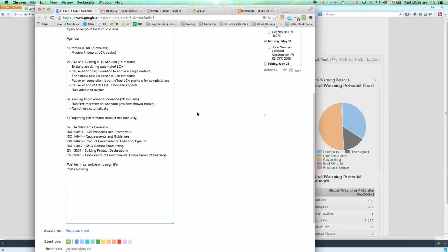You said you've been trained in NatHERS as well. Is that right? Accurate, yeah. And what we find is for the Perth climate, insulating the thermal mass, so having the insulation on the outside of the building, is a very good solution. It's quite easy in Perth to design a building that doesn't really need heating and cooling, just natural ventilation, like you mentioned, and correct orientation to benefit from some solar gain, and just insulated well, and have thermal mass on the inside.